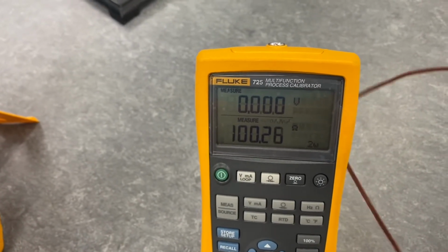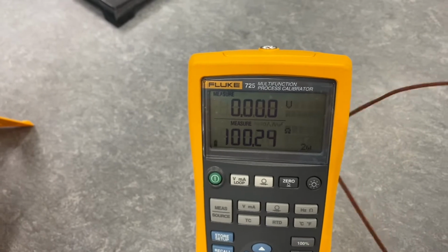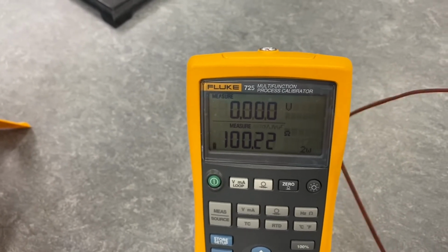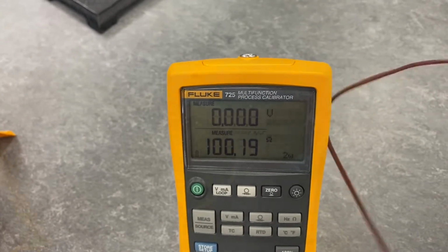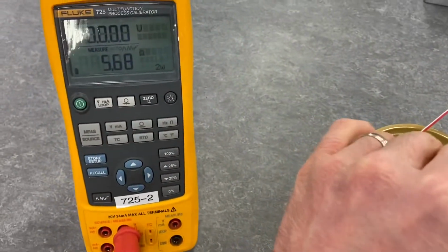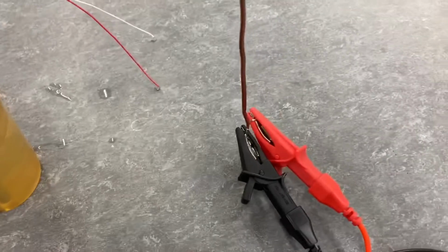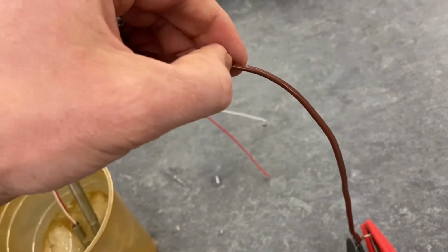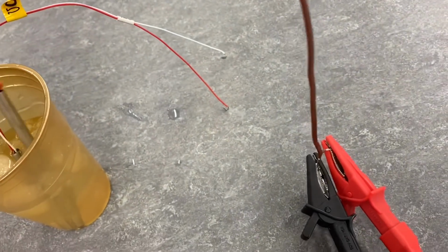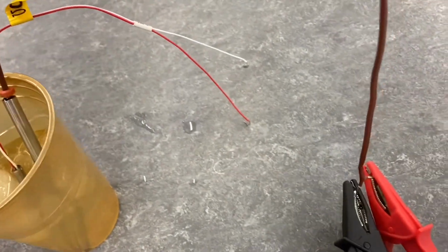So we're pretty close to 0 degrees C with this cup here. We're pretty well at 100 ohms. If we were to connect those leads now across the thermocouple, we wouldn't get that same measurement. All right, so you can see now I've hooked the leads up across the thermocouple. Another giveaway for the thermocouple is it'll usually have this brown outer jacket, a different outer jacket where they're grouped together like that to identify it.